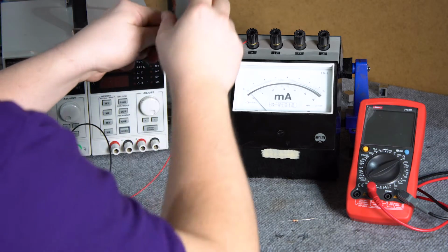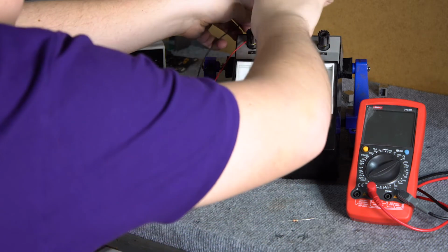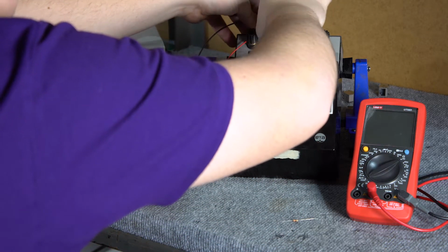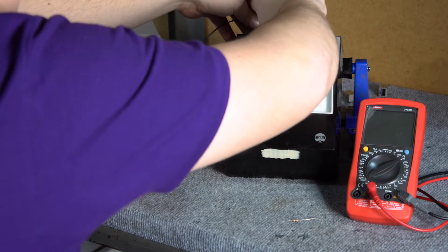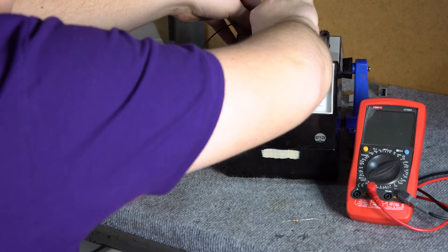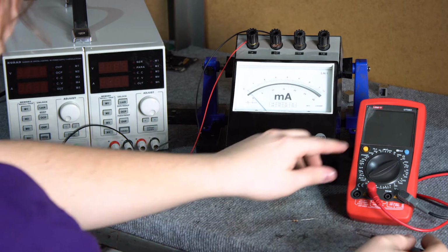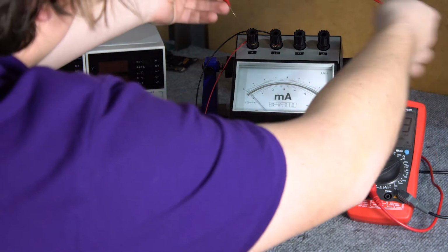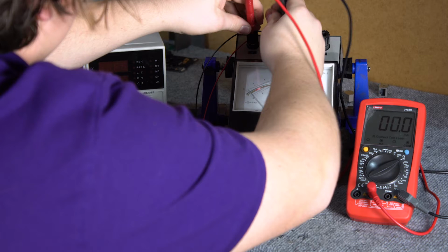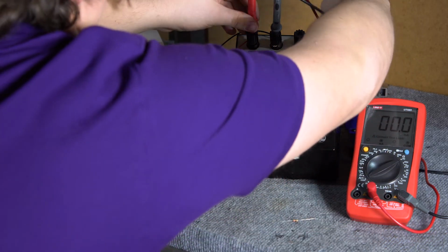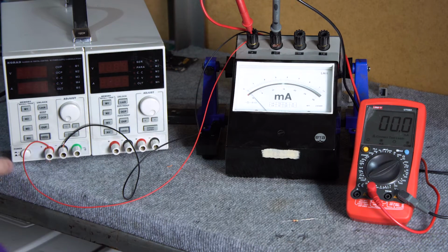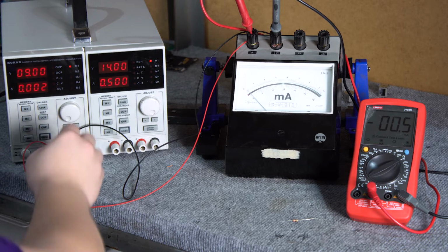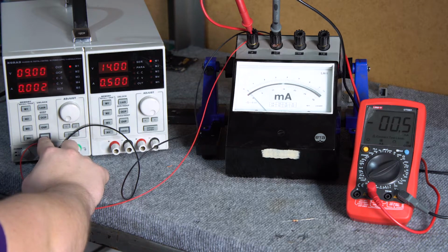We divide multimeters into analog and digital ones. The former are less and less used due to lower accuracy and sensitivity to shocks and magnetic fields. In digital ones, we do not have a scale with a pointer, but an LCD display with the right number of digits. It also contains a place for batteries or accumulator, a range selection, and connection terminals.